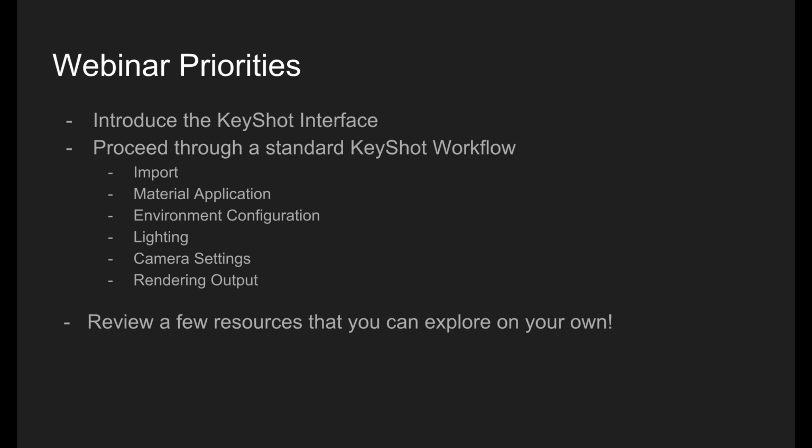So if you are using a product and you would like your light to reflect off of that product a certain way, then you would select that lighting algorithm and KeyShot will apply it to give you the most scientifically correct appearance of that product. You can always change that to optimize your appearance, and over time, as you will see, KeyShot will increase the number of rays bouncing throughout the program, increase that rendering display, and give you a progressive rendering that is CPU driven. All of that is really defined within our lighting settings.